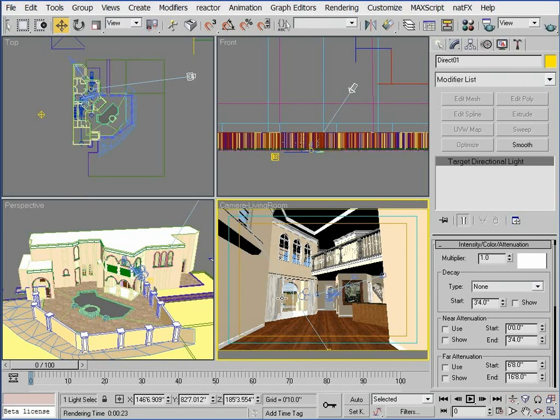And this is really an important point to understand. You really want to add the artificial lighting after you get the natural lighting from the exterior sunlight correct. If you wait until this point when the natural light is correct, you can know that when you add the artificial lights, the changes that you see are realistic or not.